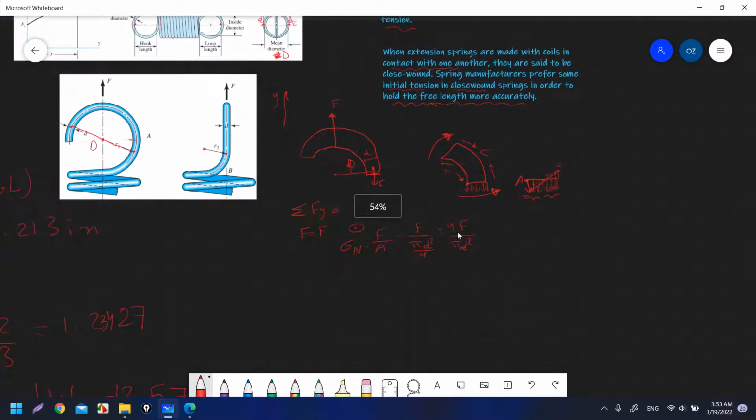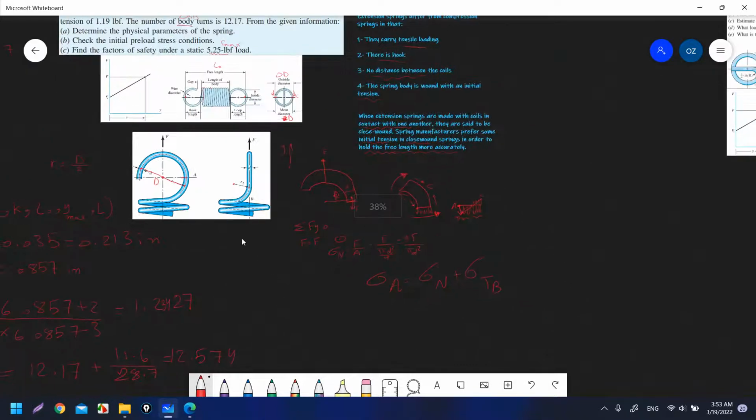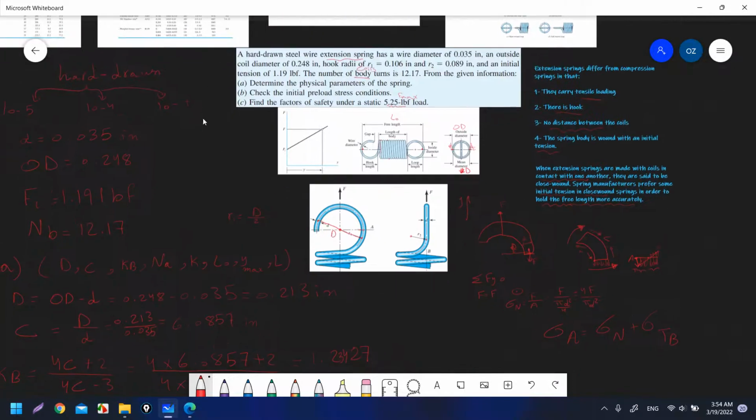So that is why it is called F max. And if you derive the equation in order to get sigma A, we will see what sigma A represents. Because it is at point A for bending, it is sigma n plus the sigma from the tensile bending. So that is the worst case, when the maximum stress will happen at this point A. That's why it is called F max.